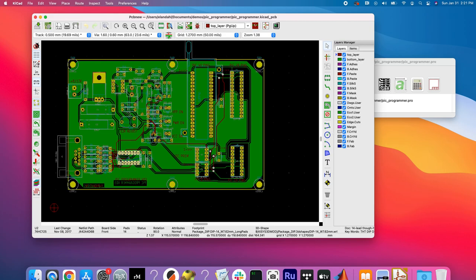Note also that on this footprint there is going to be some silk screening with an indent here. And very important, that tells you the name of the footprint package. And you'll see that those come up on the bill of materials. Very cool in these newer versions of KiCad, I'll show you this in a moment, it also has a 3D shape associated with it down here. So this is a description of the actual footprint. This is a description of the 3D shape that's been associated with this particular part on this particular board.